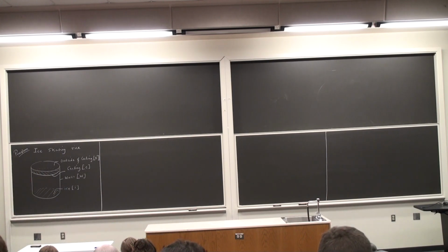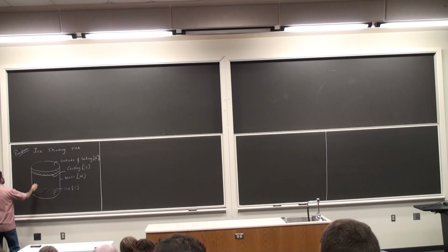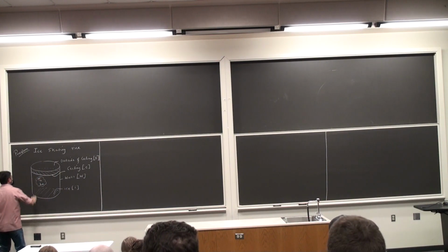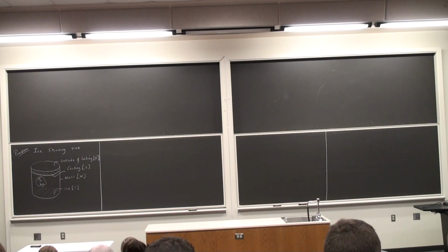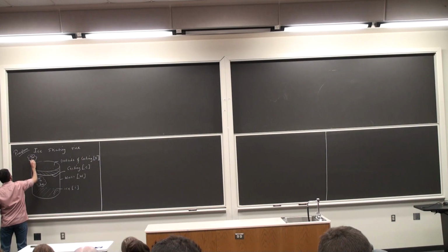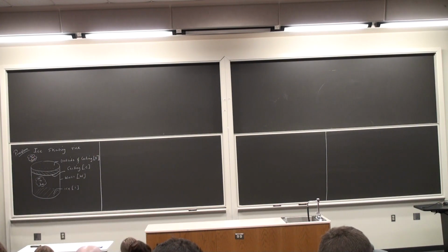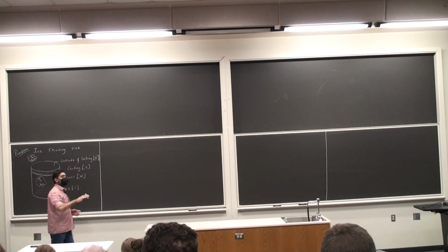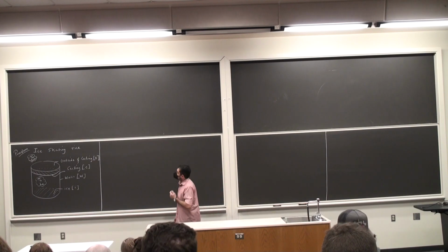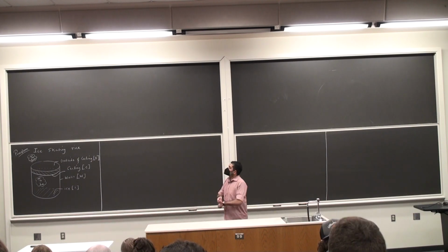There is some air within the arena, which I'm going to call little a, so T_a, h_a: the temperature of the air within the arena, and the convective heat transfer coefficient within the arena. Then ambient or outside, T infinity, h infinity. This is having a conversation with the top surface of the ceiling, the outside surface, and T infinity, h infinity are the temperature and the convective heat transfer coefficient.